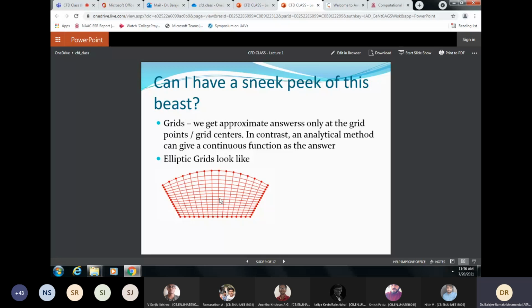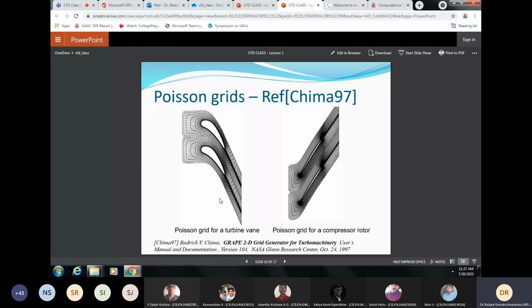This is possible if you have a rectangular grid, in the sense that physically it may not look like a rectangle, but we call it a rectangular grid. When you do some transformations, you can transform it to a rectangle. Each grid cell looks nothing like a rectangle, it's a quadrilateral, but with proper transformations, if you can express the i comma j, then you call it a rectangular grid.